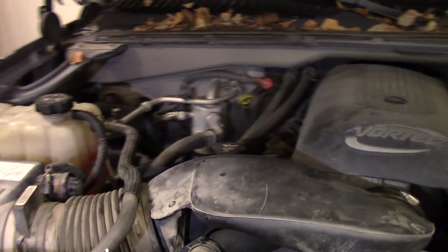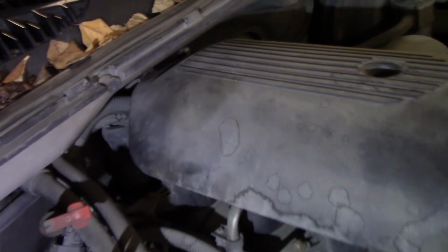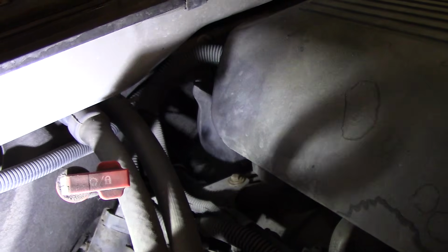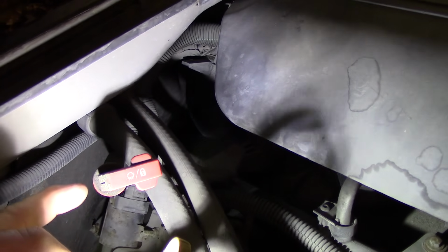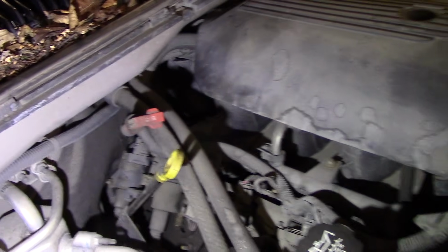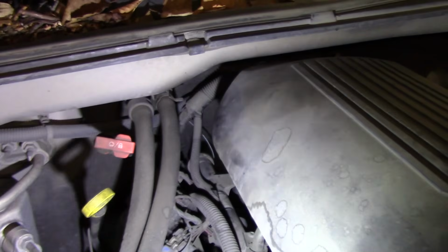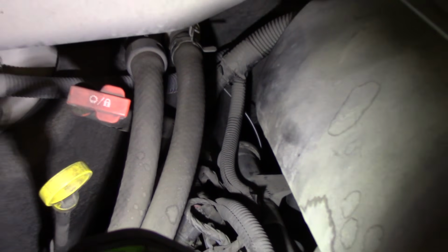And then here over on the right side rear of the motor, we've got a small ground wire that comes out of the firewall and heads down to a stud on the right rear of the motor area. There may be two ground wires, and sometimes one of the wires can break off of the stud itself. So try to get that in focus. Anyway, it's kind of hard to see there, but in this case it feels okay.